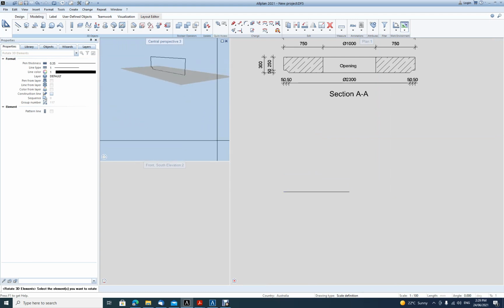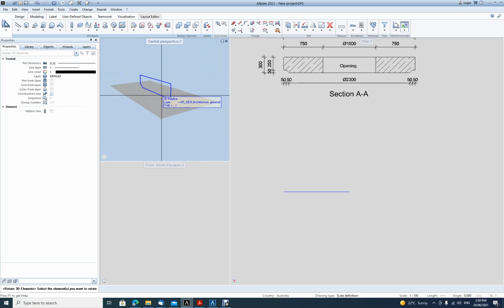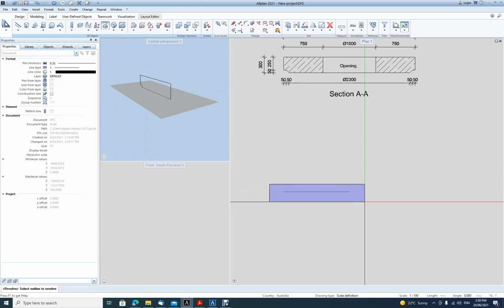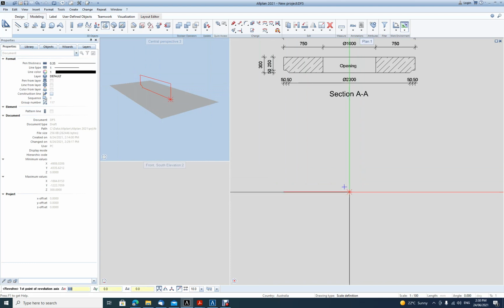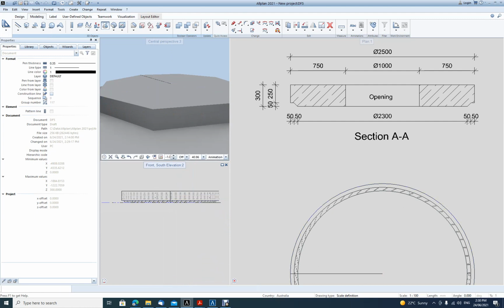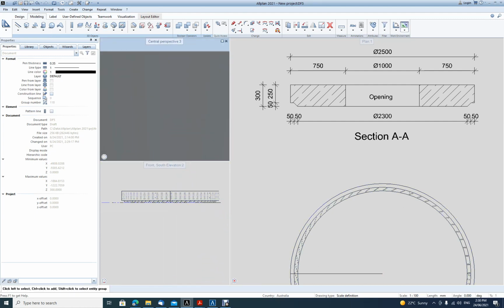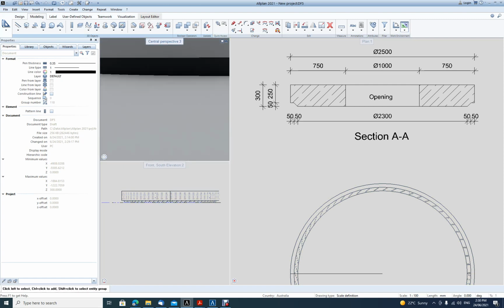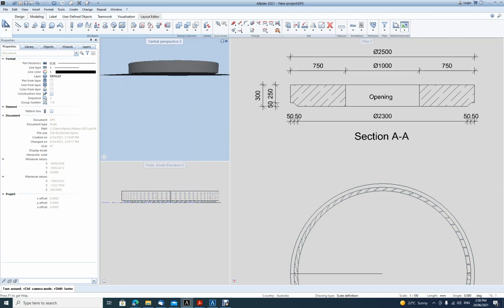half of the cross section in the animation window, and now we have two options how to create a 3D model. One is revolve. Select the elements, and then I create an X. So one X is here and the other one is going to be straight up or down beneath the element. Press escape and here you go. This is my lid.